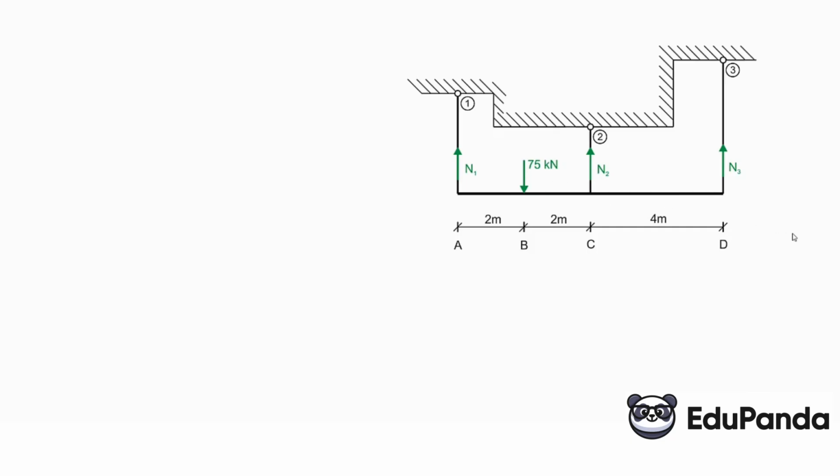From static equilibrium conditions, we can calculate the sum of moments, for example at point C. Generally, we can make the sum of moments at any point and the sum of projections onto the y-axis. The sum of projections onto the x-axis is of no use here, because all forces act vertically. We have 2 effective equations of static equilibrium and 3 unknowns. Therefore, the task is statically indeterminate.